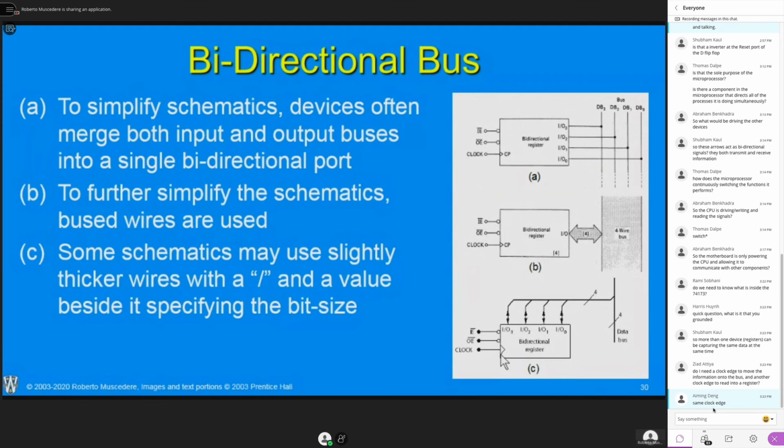Again, I would love to say schematics are standardized completely, but they're not. There's a lot of artistic license, so to speak. The oddest thing about electrical engineering is that schematics are kind of like a functional design. It's not precise. It's just an idea of how things are connected. It doesn't necessarily imply how it's physically built, so there's some level of interpretation there. Whereas a mechanical drawing is quite clear. Here's what the object looks like. This is how it's built. This is the size of this or that, or the distance between 2 points. Here, it's just a guideline. So there's often some artistic license in the way people draw schematics.